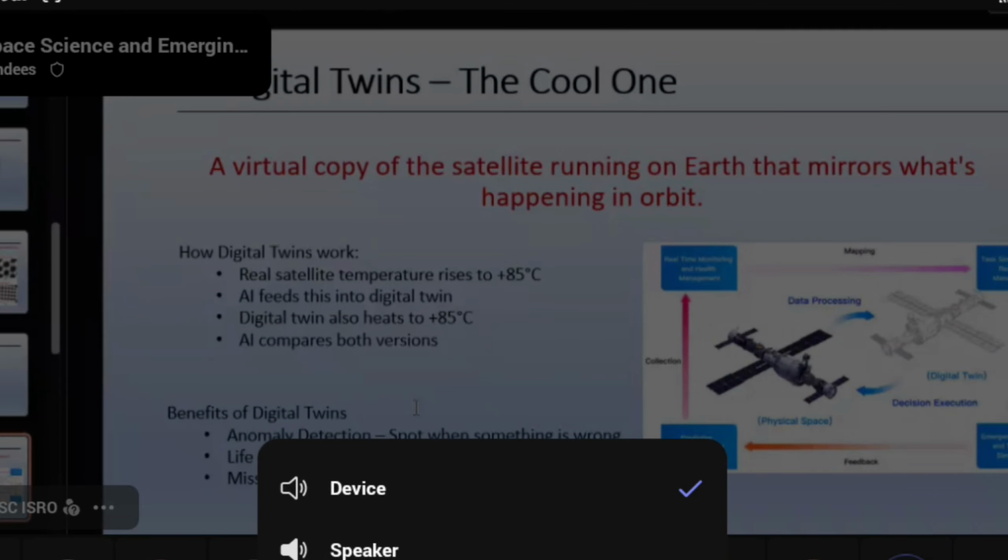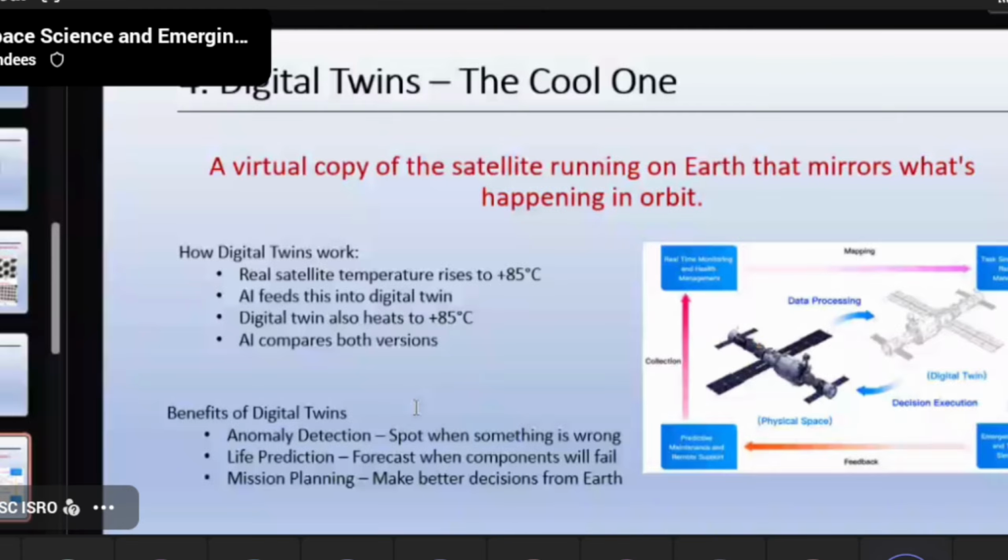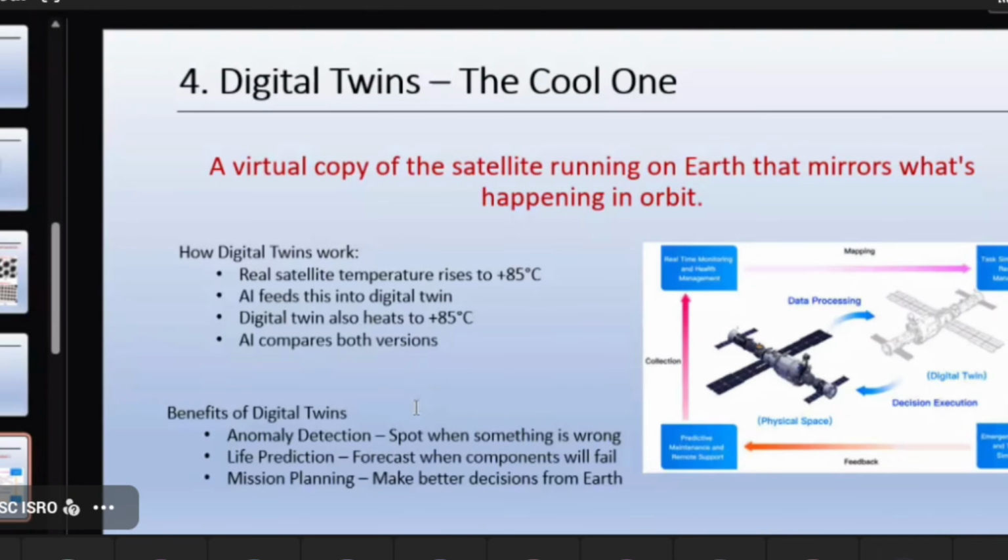So we come to anomaly detection. Now, we will subject the digital twin to extreme ranges to find where an anomaly can happen, because we know that, let's say, after 1 week the satellite is going to a zone where the radiation will be too harsh. So 1 week prior, we'll have the data, we'll have the information. Okay, the digital twin has done this, so these are the things that will suffer. They will either turn off, or reduce their voltages, current, power, whatever it is.